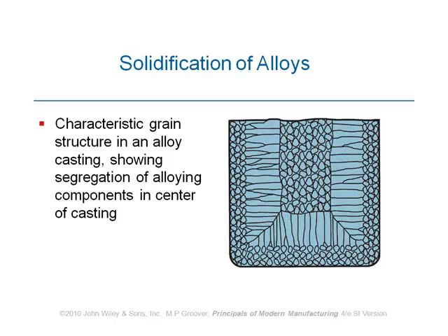How can we deal with this problem? How can we improve the properties of the material? We had that before. Heat treatment. Put the part in the furnace at elevated temperature, leave it for some time. When you are putting it in the furnace, you are increasing the rate of diffusion. And then atoms of components B and A can travel long distances inside the material.